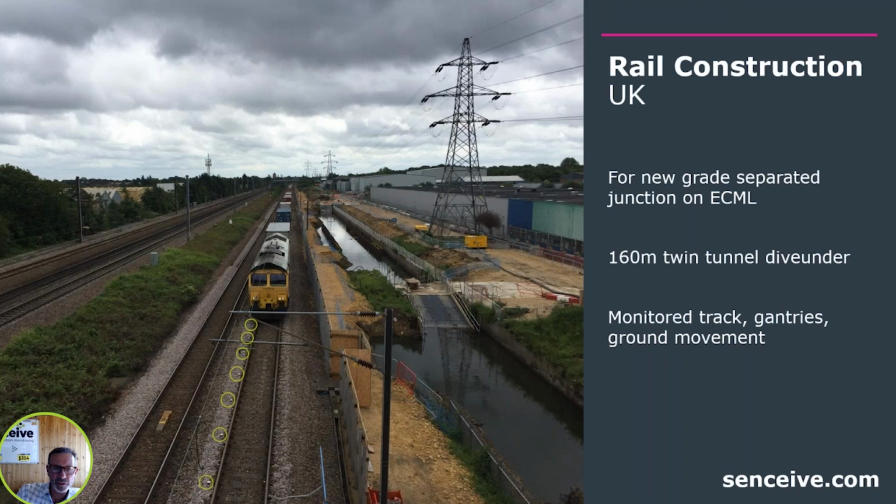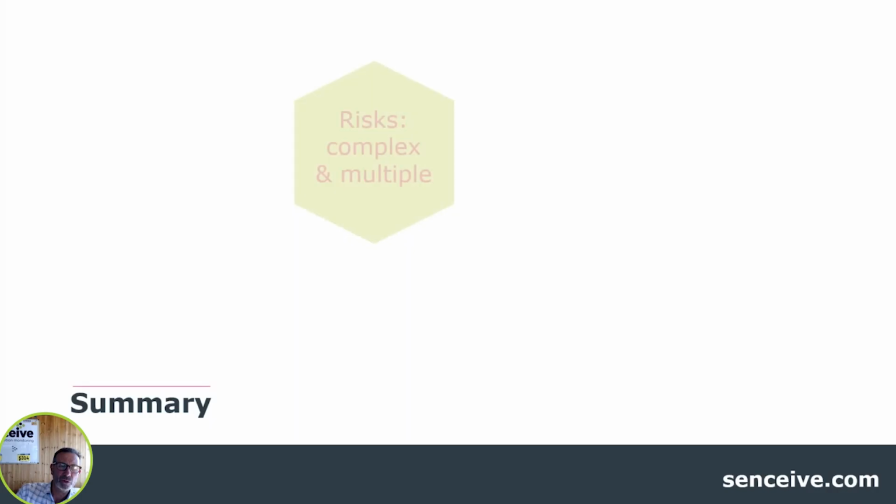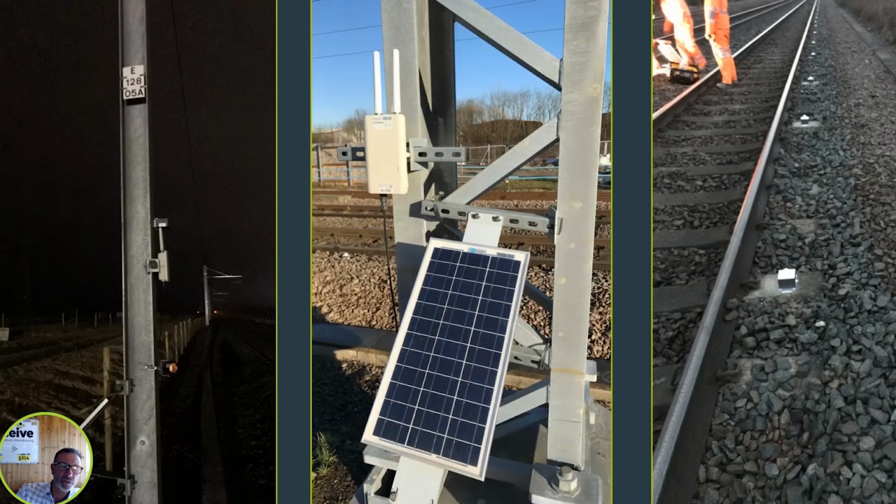A number of things were undertaken here in terms of wireless monitoring. There were sensors installed, as you can see in the green circles, on the track. And there were sensors installed on the gantries. You can see here on the left, we've got an optical displacement sensor just above a cellular gateway here on one of the gantries, which will be looking across at a gantry on the opposite side of the track. In the middle, the photograph shows the solar panel, which is powering the cellular gateway. And on the right, we've got a close-up of the tilt nodes installed on the track.